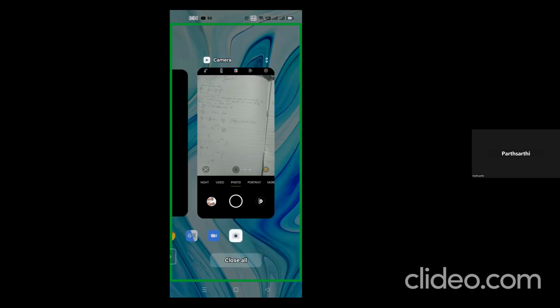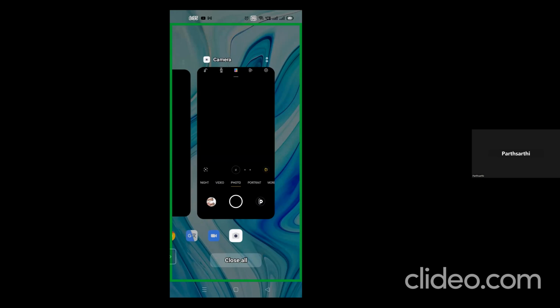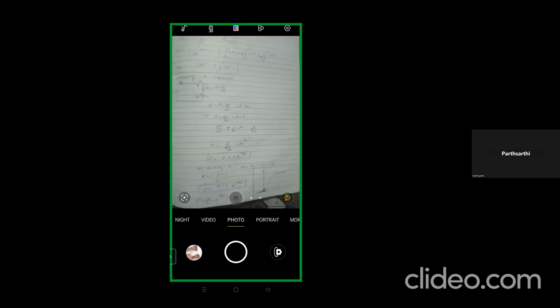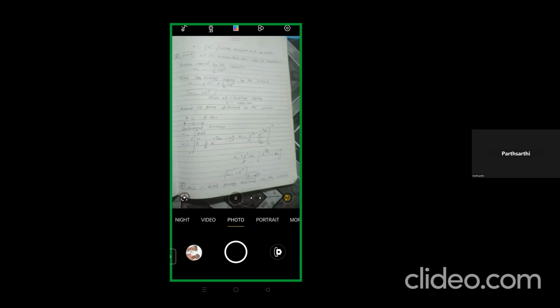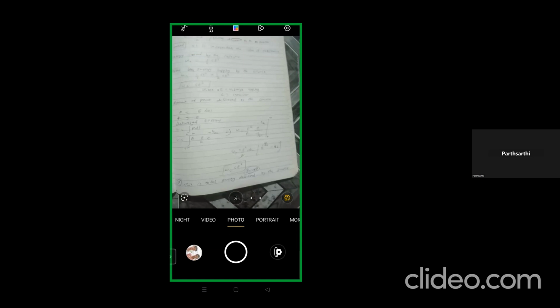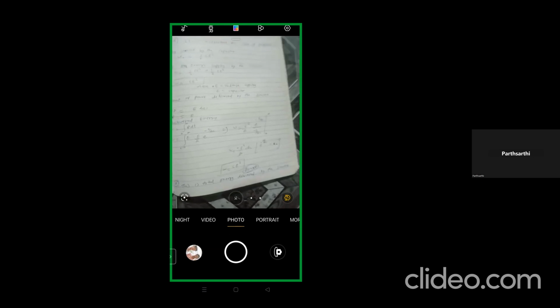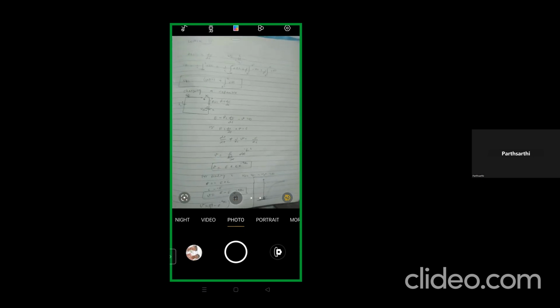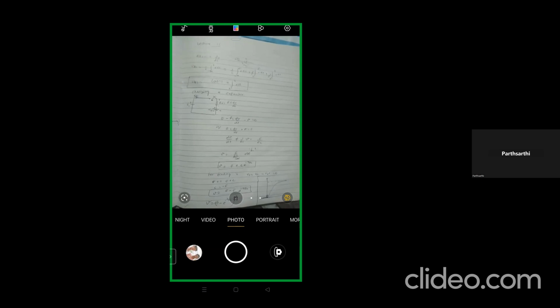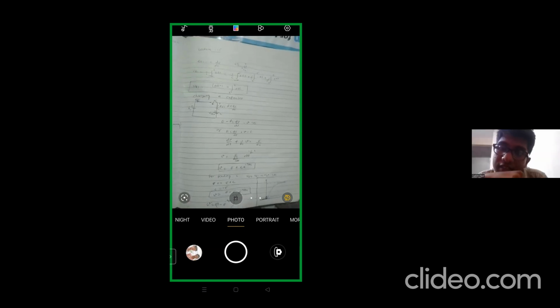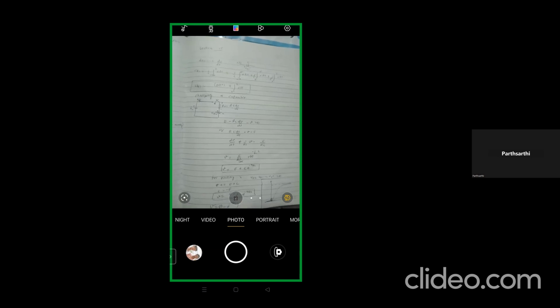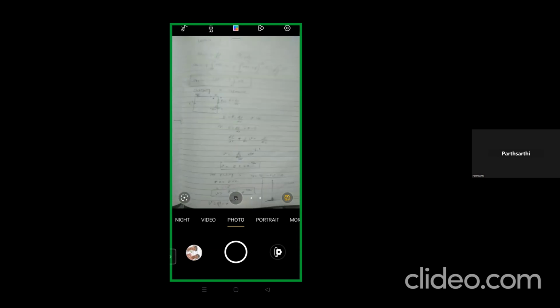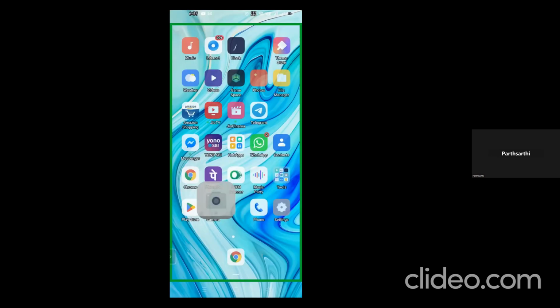Sir, in this circuit, the source is disconnected. So the energy stored in the inductor will discharge. That's why this is happening in this case, which he is telling about. Okay, so actually the source is removed, and the energy stored in the inductor will dissipate in the form of heat in the resistor. Sir, your question has a battery, so both are two different cases.